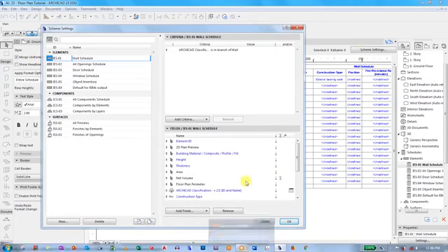And so, for the information that is not here, I'll go back to scheme settings, and there is a search button here at the left top of that pop-up window. I'll be able to search for, right now I need area, and I'll click on the search, and then settings, then here I'll click on add fields. I can search on area, and the area that I want is the area for the wall.